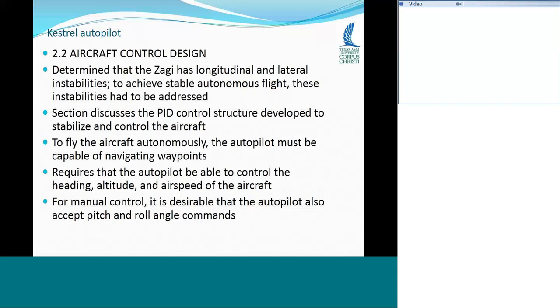Now, because it's a flying wing, it doesn't have all the control surfaces. Basically, it only has ailerons, actually, I think it may just be ailerons, because if the ailerons move together, they basically act as the elevator. And if they move separately, they act as the aileron. So when they move together as the elevator, you get pitch, and when they move independently as ailerons, you get roll. And that's really all you can control on this thing. I don't think it has, there was no active rudder, so there's no specific yaw command.